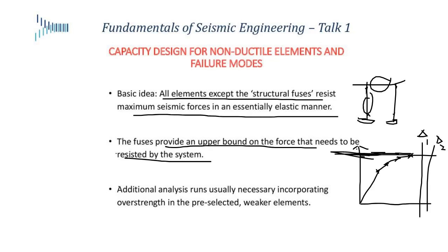Okay. So now I can design the cap beam and the foundations and the joints to be stronger than the demands that come in with respect to this force level. Now, if a larger earthquake comes along, it only puts more ductility demand into my fuses, and the fuses save everything else. The fuses save my cap beam, they save my columns from shear failure, they save the joints from failure, they save the foundations, which may even have piles. So that's how these fuses help us.